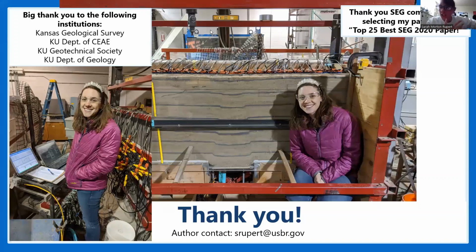For surface wave data, at least in my experience, geotechnical engineers tend to be interested in the velocity contours. And in some cases, we have some borehole data, which has density information, and we can use our shear wave velocity with those in situ density measurements to then translate the velocities into shear modulus.